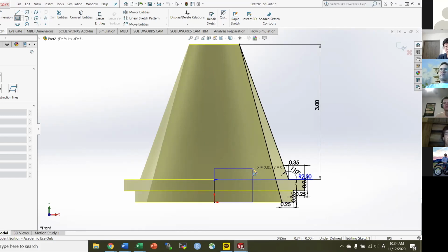It'll be just this model that started off along the axis of rotation, and it'll rotate around the axis. So it'll just create a solid without any holes inside. The key is to make no space in between the axis of rotation and the model.